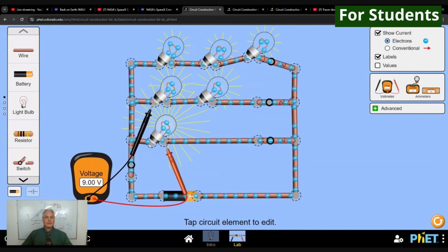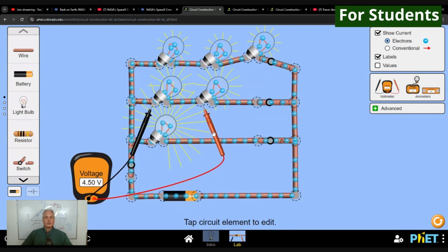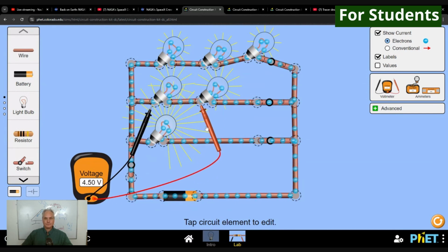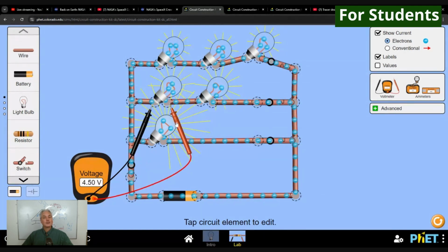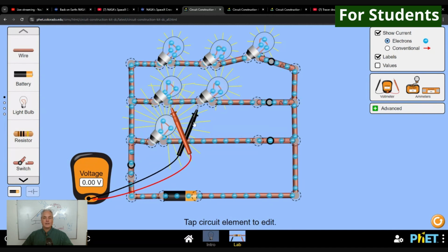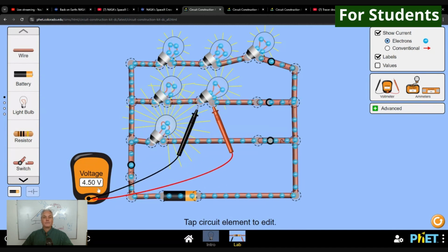Now, what would happen if here I go for the 2 volts? The 2, let's see. There we go. If I go for the electrons going from before the 2 bulbs to after the 2 bulbs, you notice here that I have 9 volts, because the 9 volts that we get here will be divided in the 2 parts right here. And if I look at how much energy is given to each of the bulbs, I have 4.5 here and I have 4.5 here.